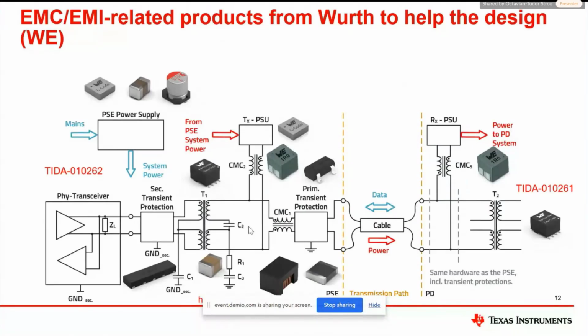And for the transient protection at the secondary side of the transformers, we have a separate ground this time, as you can see, ground secondary. And this is the ground of the PHY, and any protection devices for the PHY are referenced to this ground.